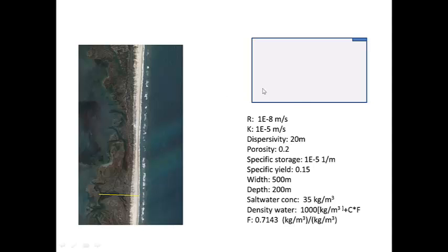And so we take that slice, and here it is represented in a very idealized way. This will be the aquifer. We'll have a constant head boundary up here that will be the ocean. We'll have some recharge coming in along the top. That'll set up a flow system like so. And we'll assume that this region is initially completely filled with salt water. Say the ocean rises and submerges the island and then drops again. And the freshwater aquifer then will develop by flushing the salt water out with fresh recharge.